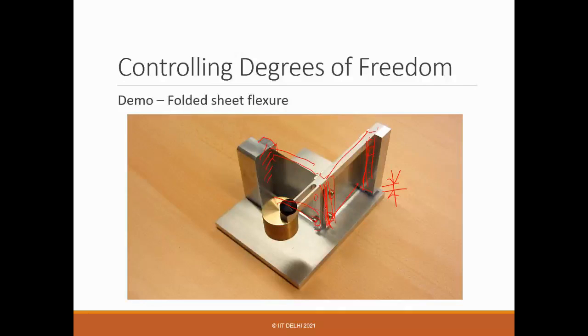So with that you don't have to bend it, you just take two sheet flexures and assemble them. But you can see a little clearance at the bottom, so that it's raised a little bit, and then at this end you connect a bar, a link here, and then you have a weight to balance it, so that you can adjust it and keep it floating. So see that if you apply a force along this direction, it's stiff, but all the other 5 are degrees of freedom.